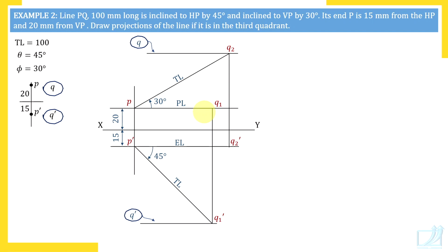Rotate PL, what does that mean? Listen, this horizontal top view PQ1 has length PL. 3 top views, you know, PQ, PQ1 and PQ2. That PQ has the same length PL. PQ1 is through P. Similarly, PQ, this line is also through P. So, we'll rotate PQ1.